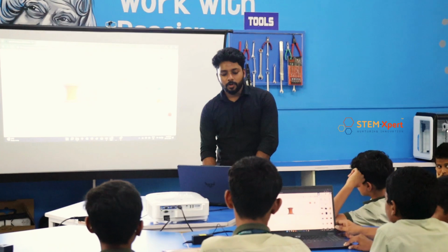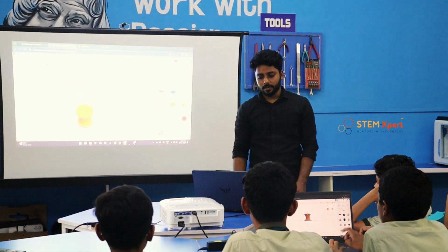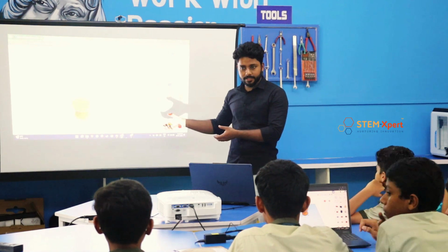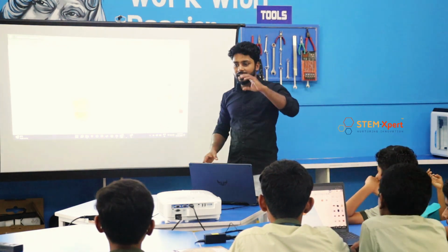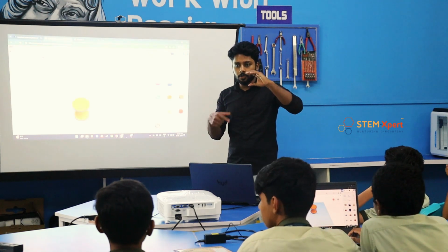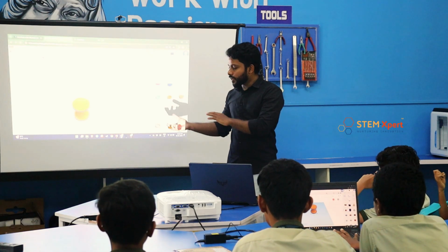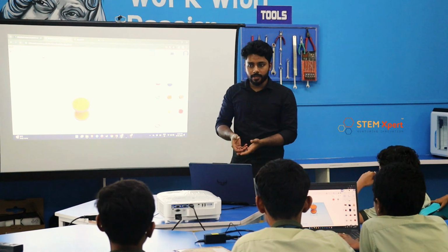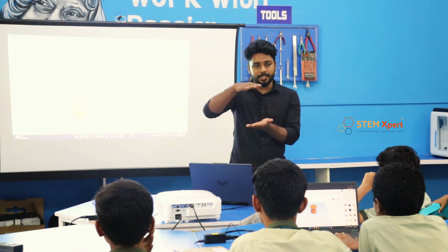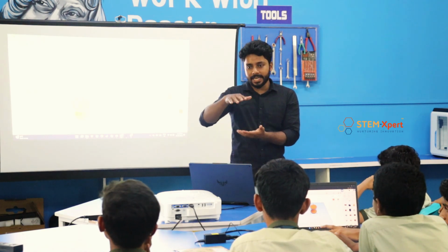Now let's go back to the home view. So here we will be having a shape like this, right? But we don't need this much height. We need to reduce this height to 20 again. So we are converting the size to 20. Okay, 20 in the sense only the height is changing. Okay, not the length and width.